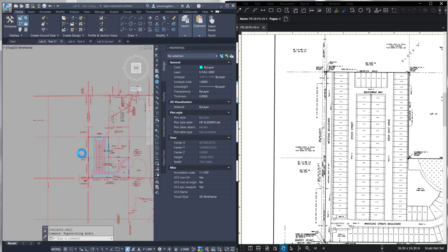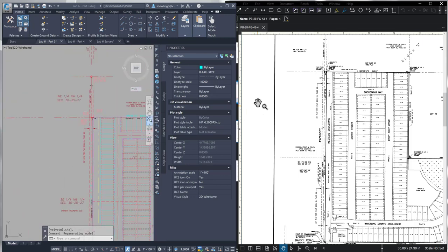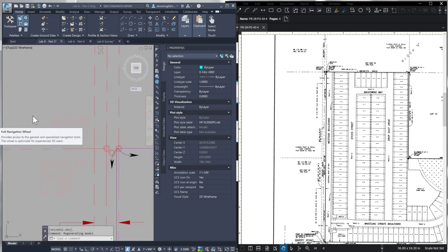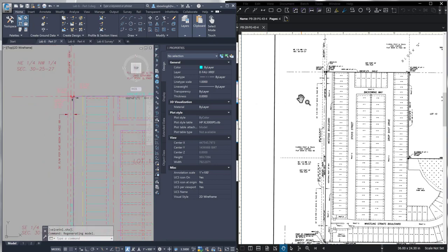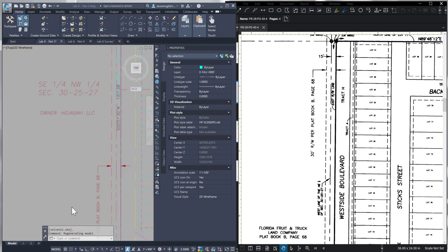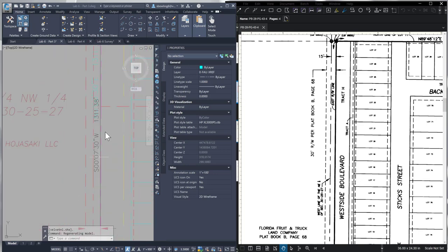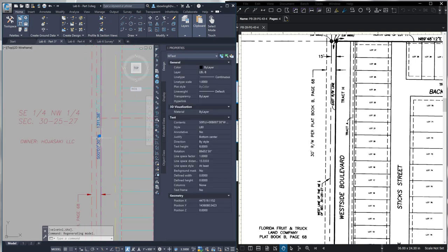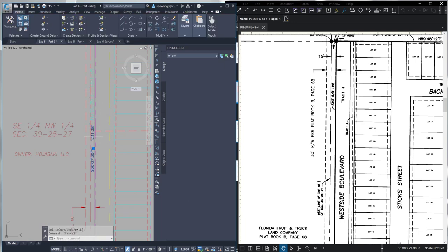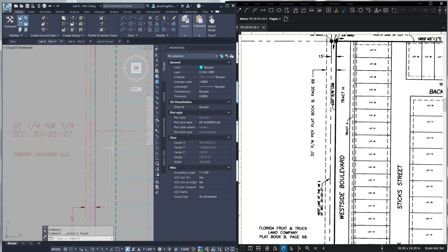So if I'm looking at this, I'm interested in this area. We can see that they have that labeled. You can see that this is labeled. You can see this information up here is labeled. We do have additional labels here, so we'll need to add that. So the east right-of-way line. You can see that our label, if I pull this out, is the exact same one. So I'm going to delete their old label. I don't need theirs.